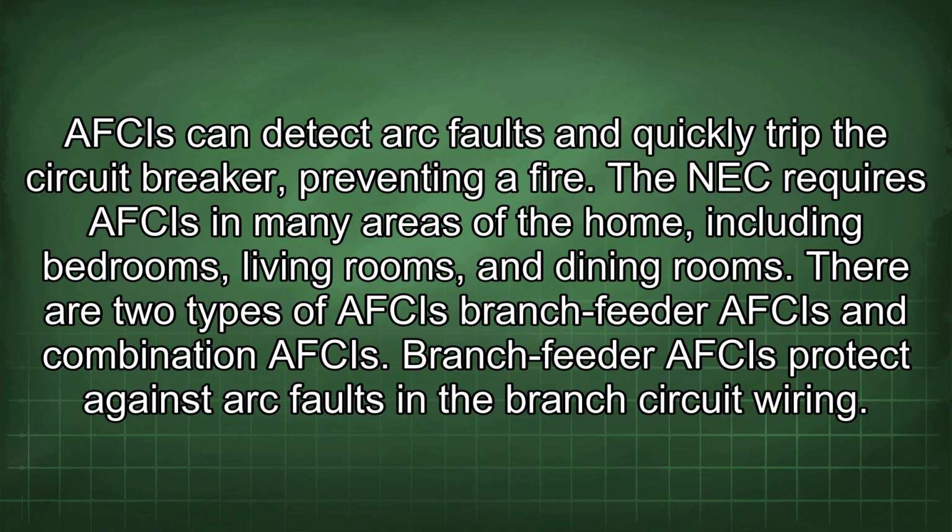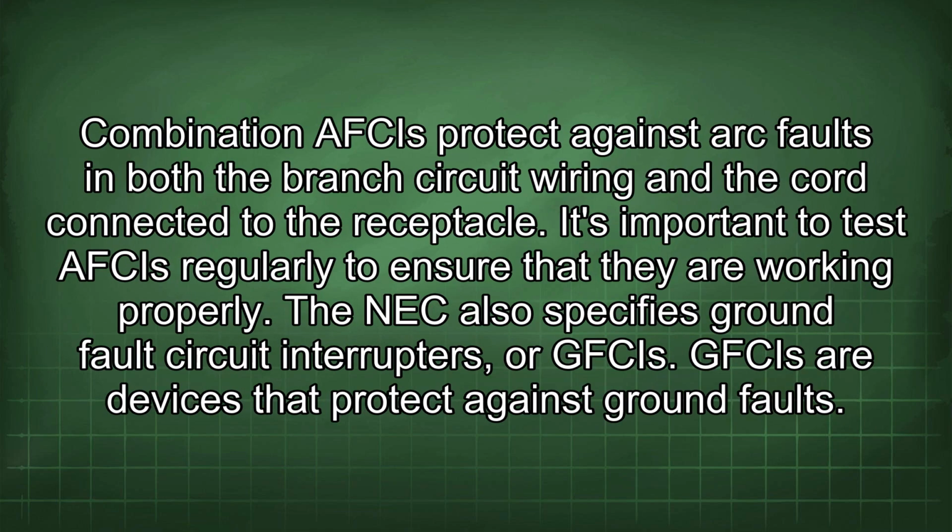There are two types of AFCIs: branch feeder AFCIs and combination AFCIs. Branch feeder AFCIs protect against arc faults in the branch circuit wiring. Combination AFCIs protect against arc faults in both the branch circuit wiring and the cord connected to the receptacle. It's important to test AFCIs regularly to ensure that they are working properly.